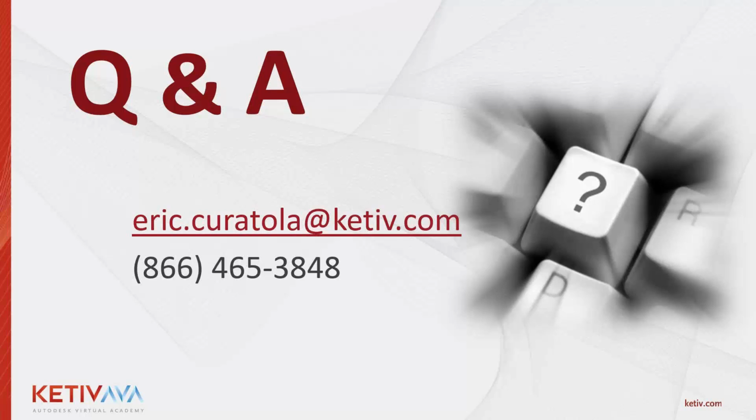Kathy asks, can my 2015 or 2016 Revit files be read in the 2017 Revit version? Absolutely. All Revit files do upgrade forward, so 2015 and 2016 can open in 2017. The one thing to be aware of is once you've upgraded them to 2017, you cannot take them back. So if you're working with somebody in your company, or with contractors or anything like that, you need to make sure that everybody is on the same Revit version.